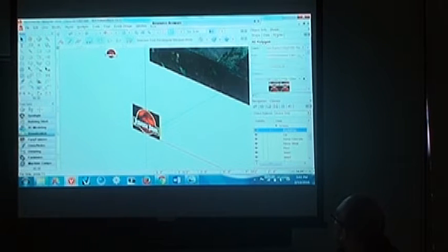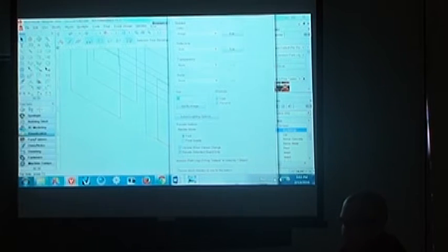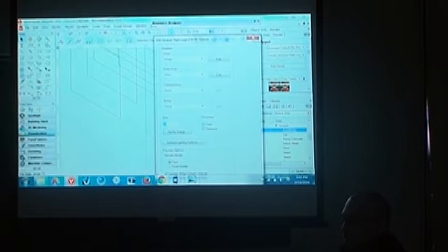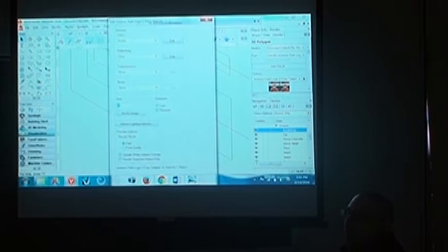And if I go to render, you can see right here, this is the texture that it automatically created. Okay? And I can quickly edit that texture by clicking right here and going to edit texture resource. Now, did everybody notice that button that said constant reflectivity? Okay, because I checked constant reflectivity, it added this glow to the texture.